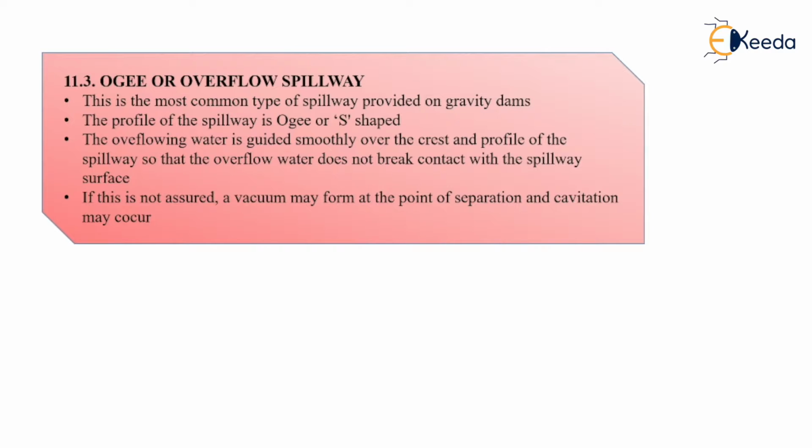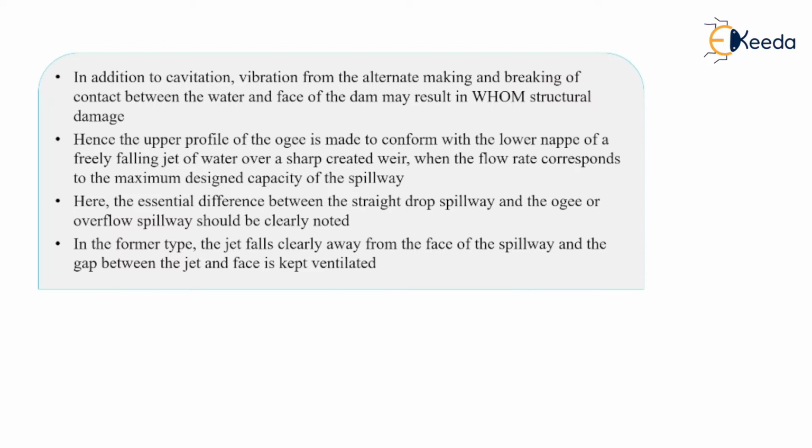If it is not assured that the overflow water continuously makes contact with the spillway surface, vacuum may be formed at the point of separation and cavitation may occur.